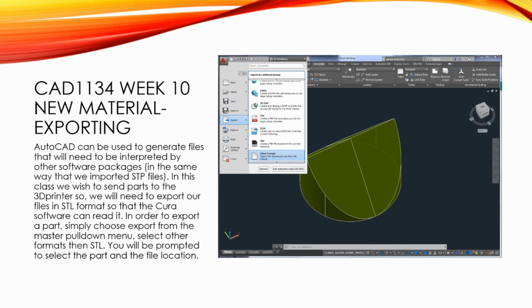But you also want to be able to output an STL file. STL files are great because that's what 3D printing software uses. And so we have available to us Cura, which is a software that can read an STL file, and they call it slicing. So they'll take a solid piece of geometry and slice it in layers so that it can print it. And we're going to talk about 3D printing here in a second.